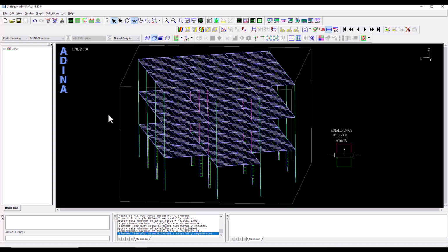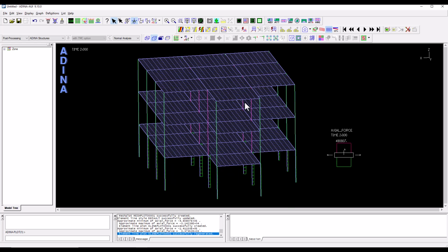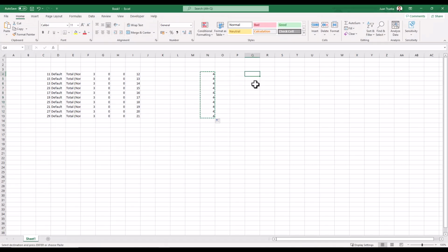So we could take, for instance, our pressures at the floors, and we know that we have a distance of 5 by 5. So let's go to a spreadsheet again. We have an area of 5 by 5, and we have a pressure of 5,000 that we applied, and we have 10 surfaces in total per story.